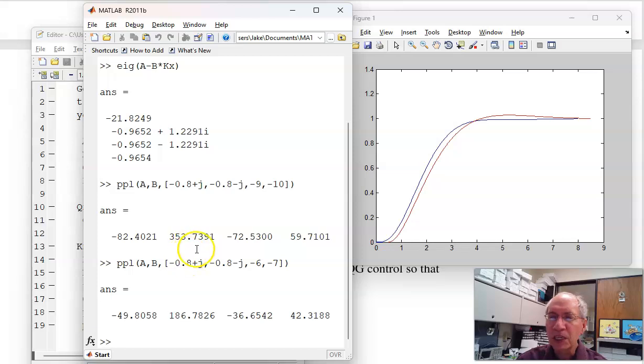Again, with pole placement, I don't really know where to put the non-dominant poles. They don't really affect the response, but they do affect the feedback gains. The advantage of LQR methods is you get a decent response, but you tend to get smaller gains because I'm weighting the input squared. So here's the feedback gains, and there's my step response shown in blue.